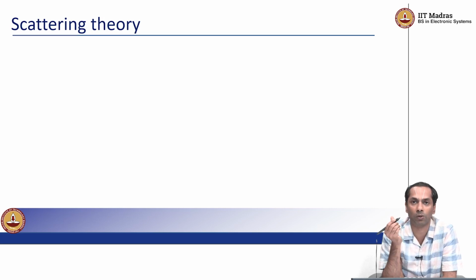Remember, we only calculated the fields as solutions to a rectangular waveguide, right? Now, if I were to say bring in some interruptions, right? One way to design filters is actually to insert various discontinuities within the rectangular waveguide, right? As metallic rods in very specific locations at certain depths, right? So if we were to analyze these situations, it can quickly get exceedingly complex, right?